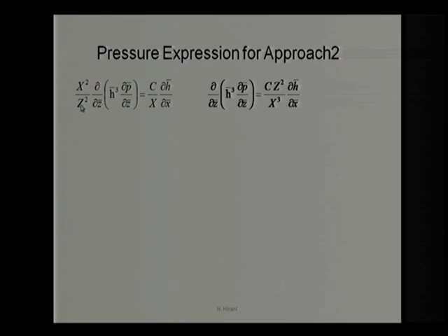We can take the z square this side and divide it by x square, rearranging a term. So now there is a clearance dimension or maximum dimension in z direction, max dimension in x direction, and an additional point is that h bar, the film thickness, does not depend on the value of the z coordinate. That is for a steady state one directional motion only. Otherwise, it may depend on the z coordinate.